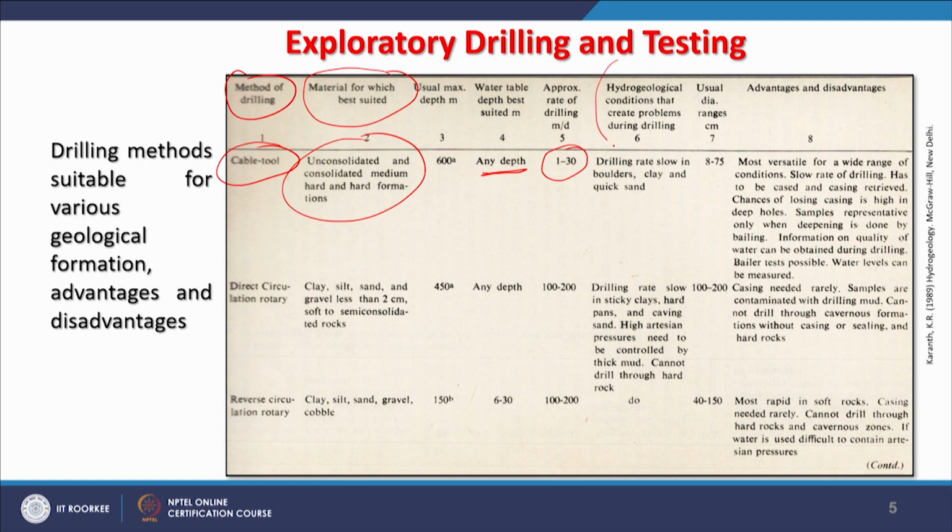Now, the hydrogeological conditions that create problems during cable tool drilling: the drilling rate is slow in boulders, clay and quicksand. So if these are in the subsurface, there might be some problem. The diameter achieved for the borewell through this cable tool method is between 8 and 75 centimeters.